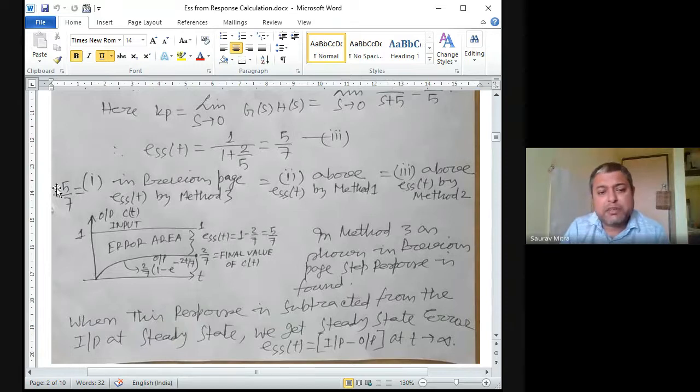So from the open loop transfer function, we can estimate what is going to be the stability of the closed loop transfer function. Because if this output is getting steady at a certain value, that means this is a bounded kind of output. In that case, the system response is not going to be unbounded. So the system will be stable, or marginally stable here, but at least it is not going to be unstable.